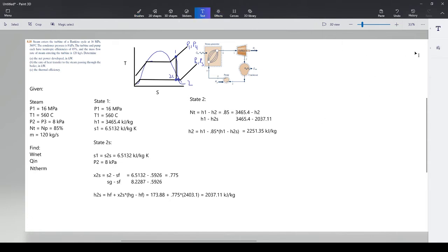All right, so we are there. Now we are past the condenser, actually. So state 3 is after the condenser. And the job of the condenser is to lose all of the heat, right? We're trying to throw all the heat out of the cycle to get it to go through the pump, because we want this to be a liquid pump. We want it to have no vapor or gas in there. So we want all liquid, therefore the job of the condenser is to make it get to the pump as all liquid. So we are going to assume that all liquid is going into the pump, which is x3 equal to 0.